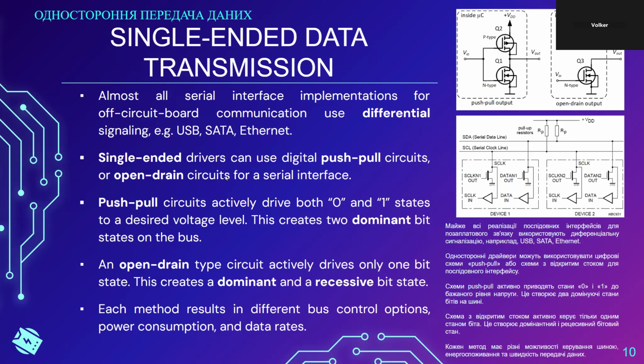If one output is trying to drive a signal high and another output connected to the bus is trying to drive the same signal low, then you're getting a large error current. Large in this case would be 40, 50 milliamps, which is large in terms of microcontroller circuitry. So you have the advantage of higher speeds and the disadvantage in bidirectional buses of possible high currents under error conditions.